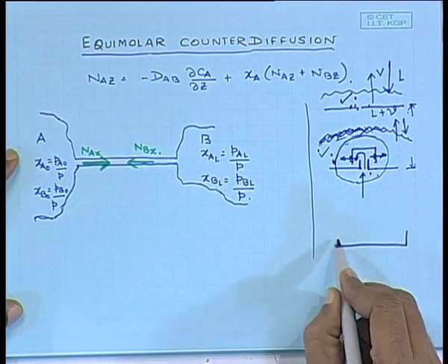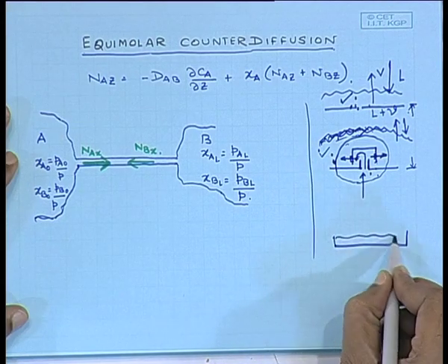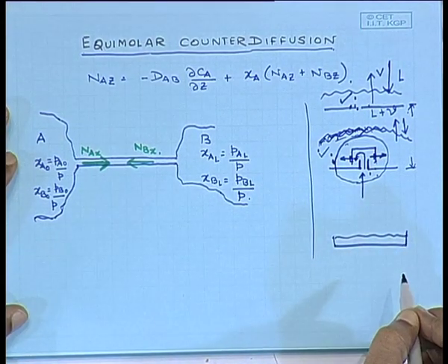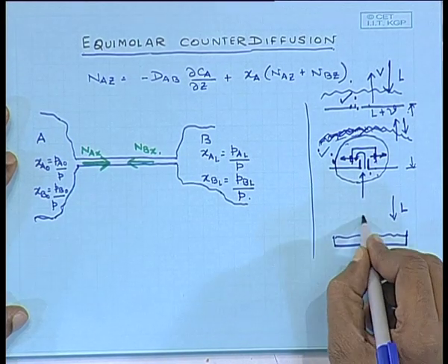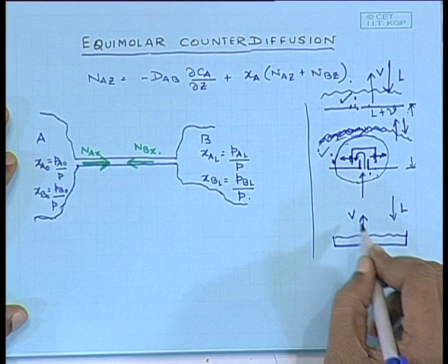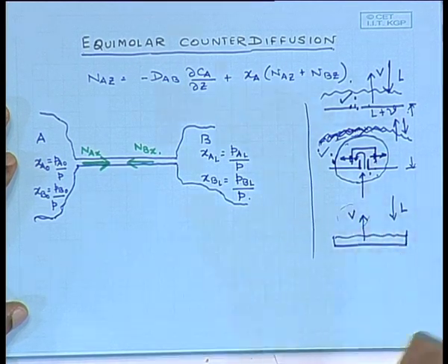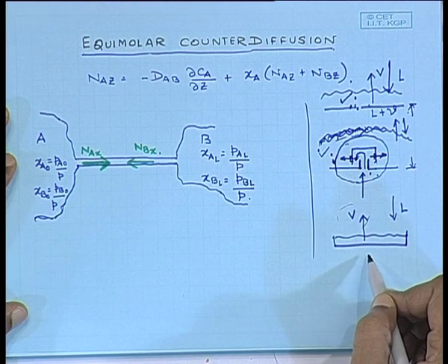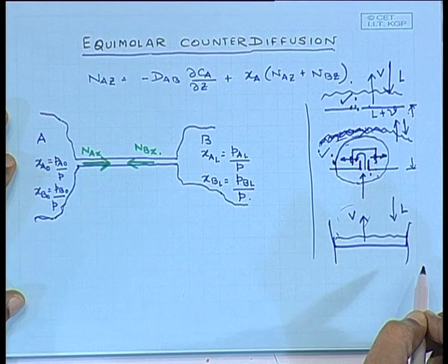I will repeat my question again. This is my tray, let us say a very simplified figure of one tray containing some agitated liquid vapor mixture. I have liquid coming from the top and I am generating some vapor such that I get some amount of enrichment. In order to generate the vapor, as he has suggested, I need some energy from outside, but these are all insulated. So, where would you get the energy from?